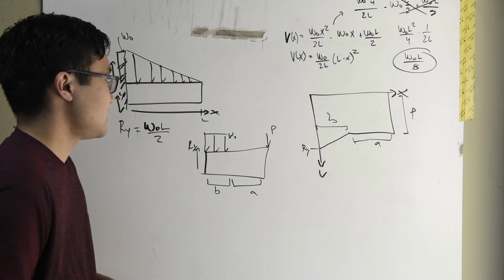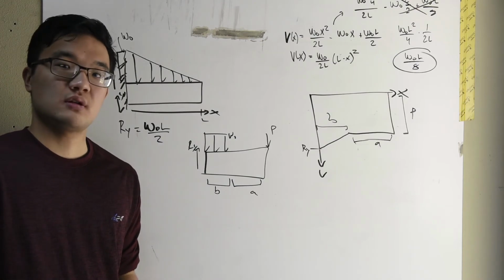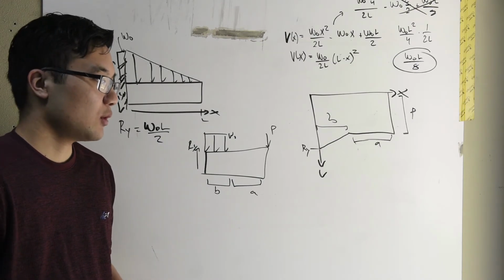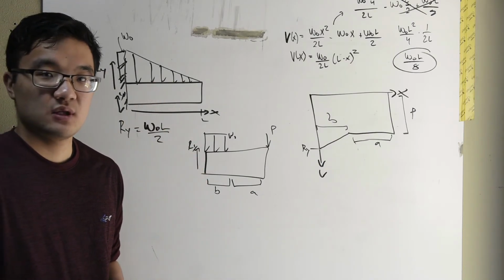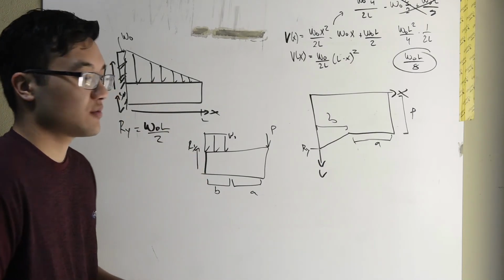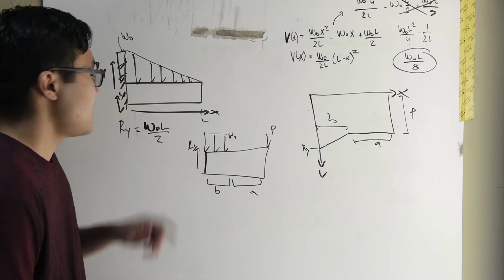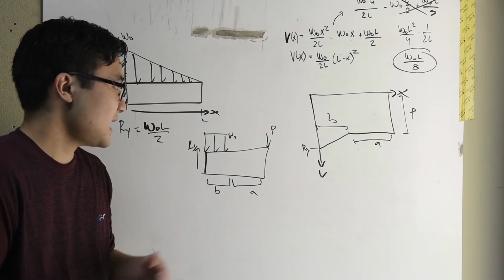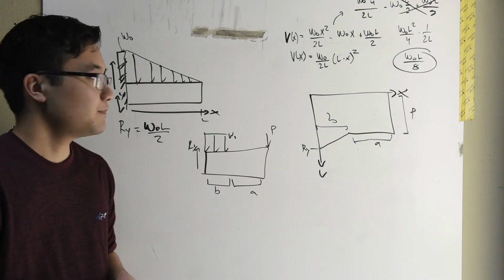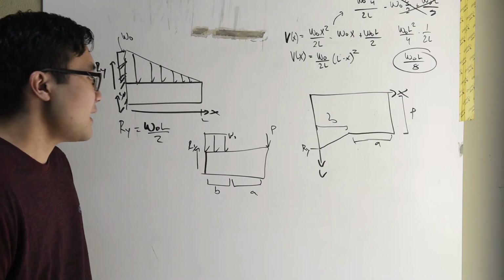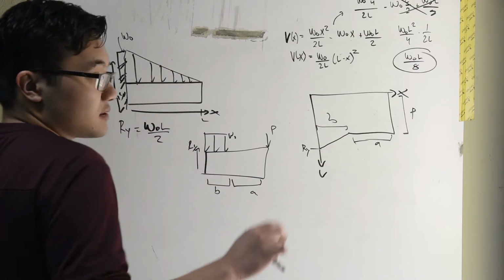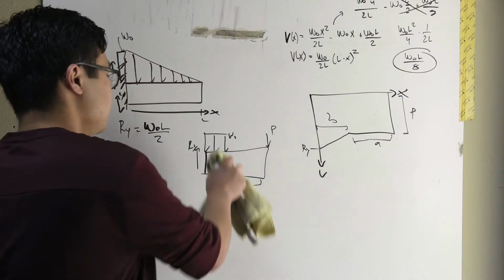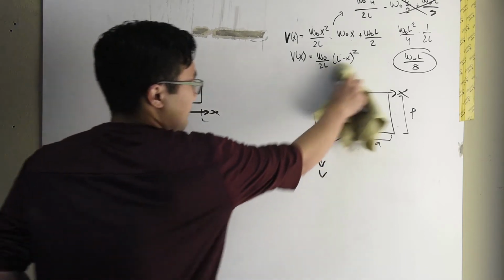So as a structural team, as long as you know what your distribution looks like, as long as you know what the lifting force is on the wing, that's the distributed force, you can go ahead and calculate for how strong your material has to be at the support or at any point in the wing. What this does is it allows us to say, okay, if we have our diagram, let's jump back just a bit. I want to make one more point.